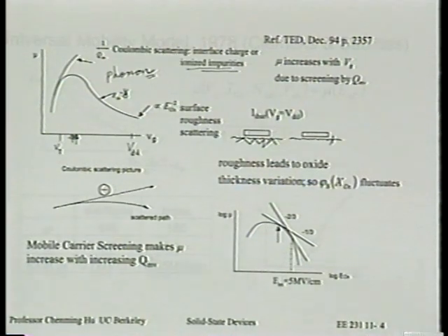When we say the mobility, is it the bulk mobility of the silicon? No. Any mobility we say in this section, this chapter, maybe in this course, is the surface mobility. Only the inversion layers, the only mobility we're interested in. And also, in previous lectures, we said that the inversion layer is slightly under the surface, so it doesn't go right through the surface. It doesn't matter. In that case, you have to interpret the surface a little bit loosely. Wherever the current is flowing, we're measuring the mobility.